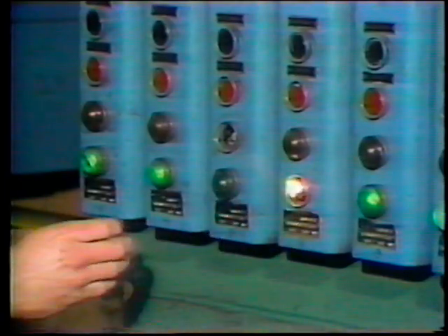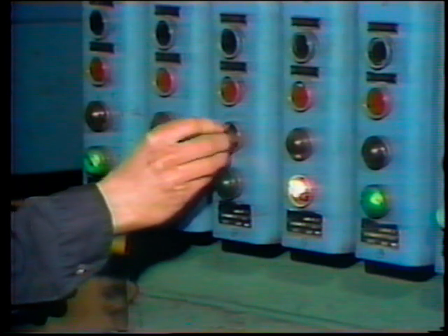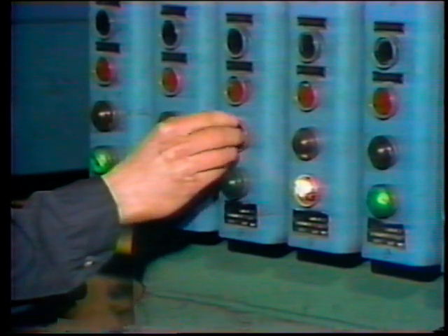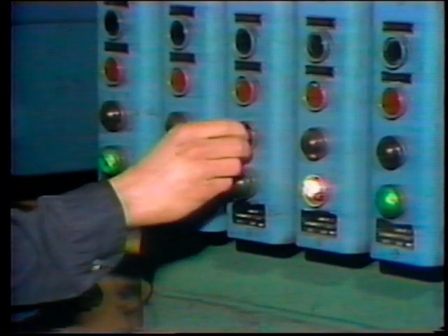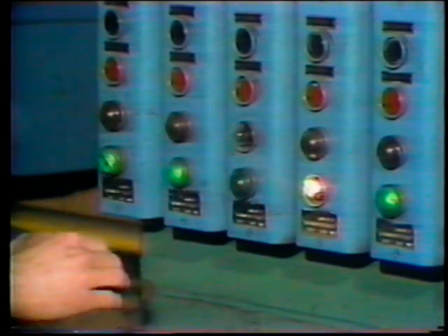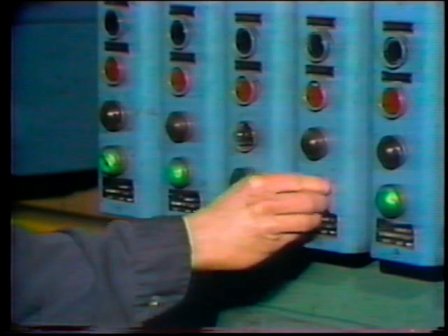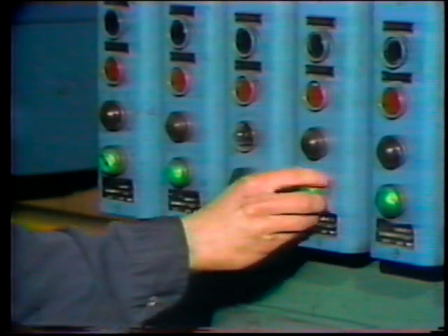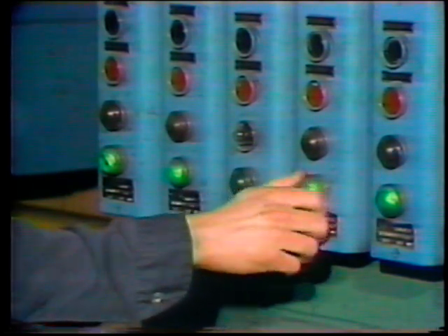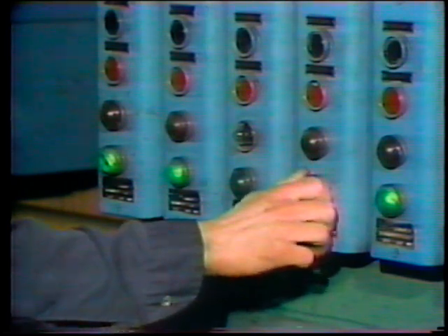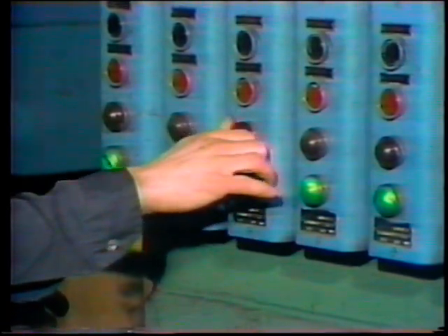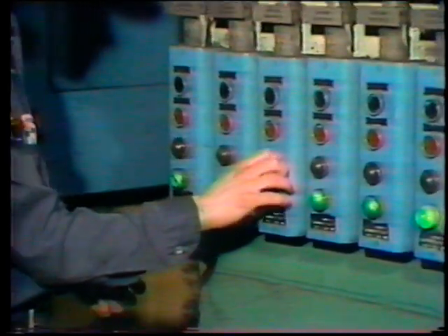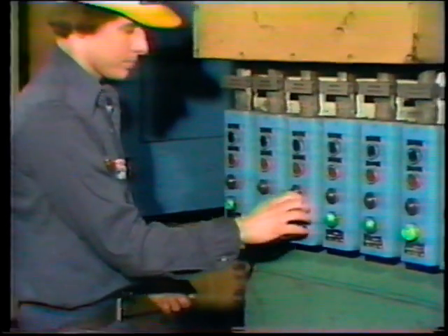After finding out the symptoms of the problem, the electrician replaces the indicating lights at the push-button station of the malfunctioning controller with indicating lights of an adjacent push-button station. This is to make sure that the indicating lights are not burned out and giving false symptoms. The electrician discovers that the indicating lights are all right and should operate correctly. The electrician then refers to the schematic of the motor controller.